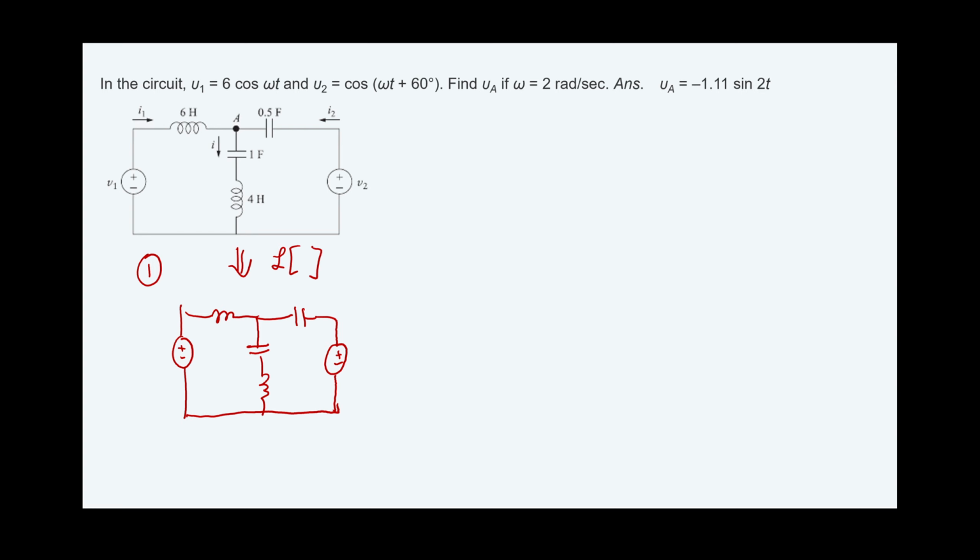So meaning in time domain V1, we convert V1, so V1 is equal to 6 angle, what is the phase angle here? 0. Now you might wonder, where's the omega? Omega doesn't change, okay? Because it is the system. If you can remember, S is equal to alpha plus j omega. That is the root of the differential equations, meaning your system's characteristic can be expressed by omega, but it's not the concern of the analysis, no? The problem here is looking for VA.